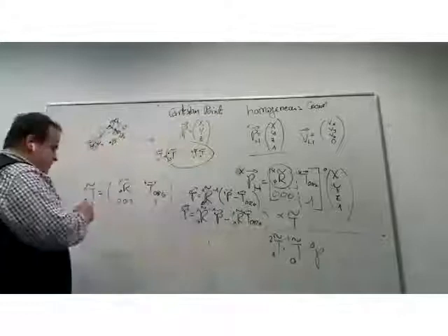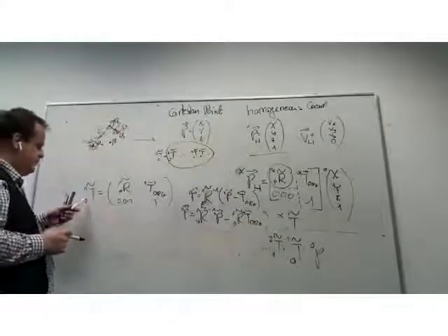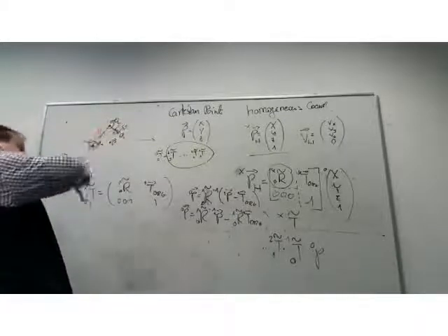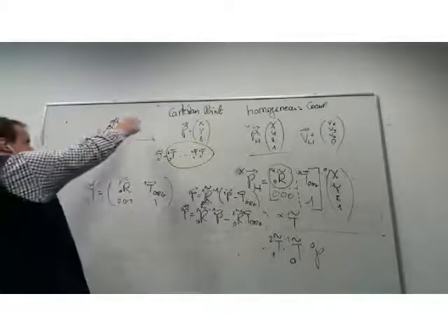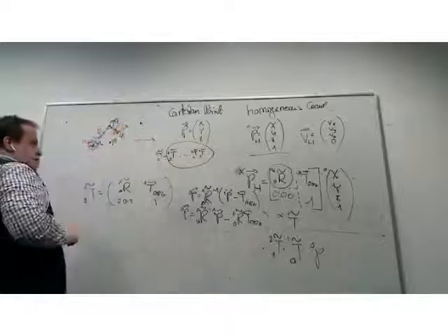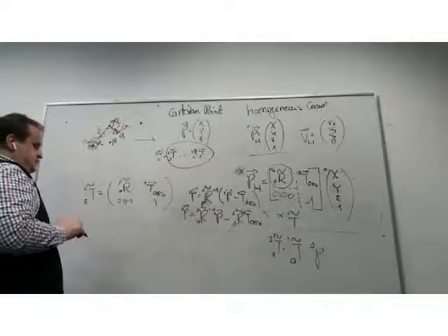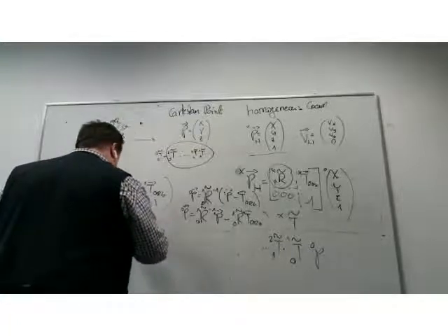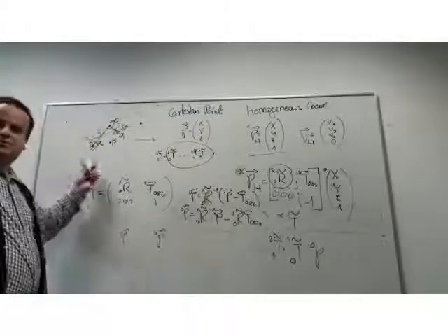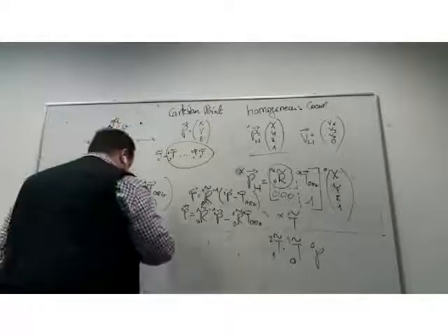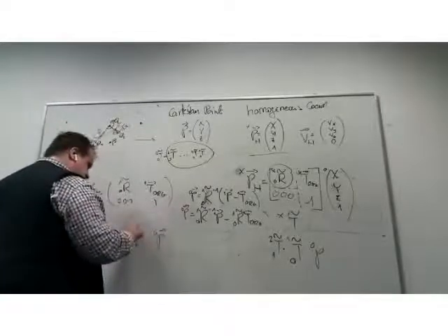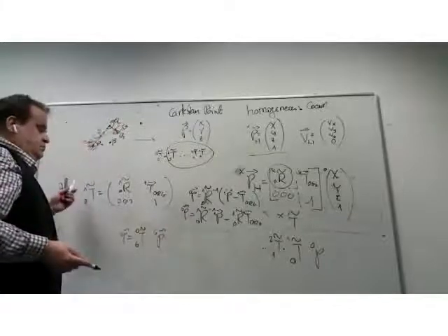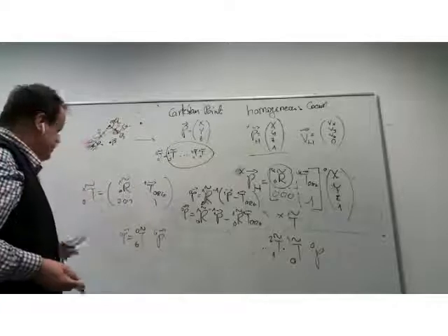So if I know the transformation matrix to go from 0 to 1, and I want to go in the other direction, I would like to transform. I know the representation of the point in the 6th coordinate frame. I know P6. And if I want the point in my 0 frame, I will multiply by the inverse matrix going from 6 to 0. Similar to what I did here.